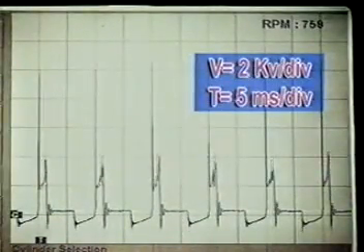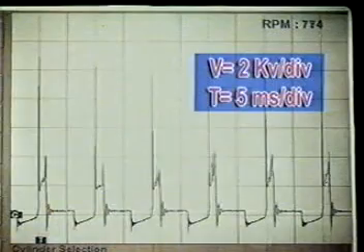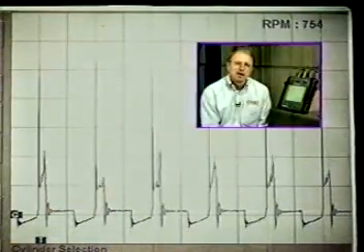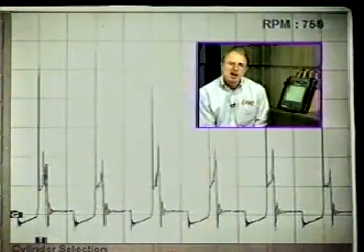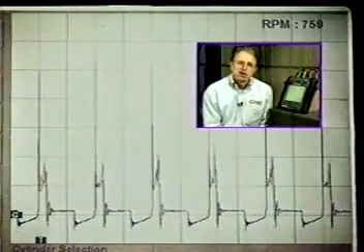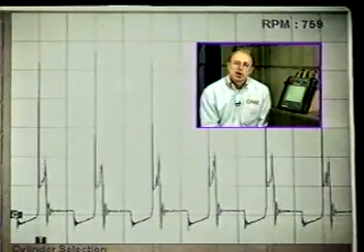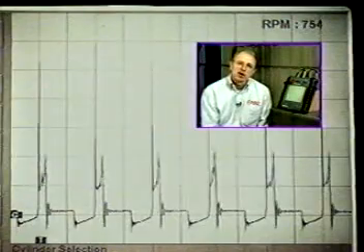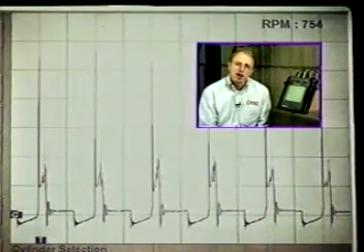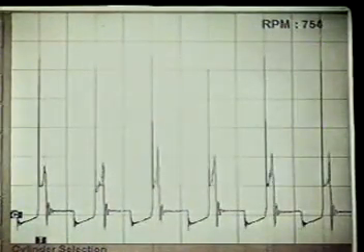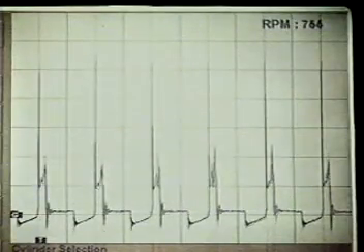You're looking at a parade pattern on the secondary right now. You will notice that you're firing roughly about 10 kV. Now what I'd like to do here before we get out of this parade pattern is a wide open throttle snap, and what you're going to witness is the firing voltages are all going to go real high, verifying that compression is good and the volumetric efficiency of the engine is good. So let's give it a wide open throttle snap.